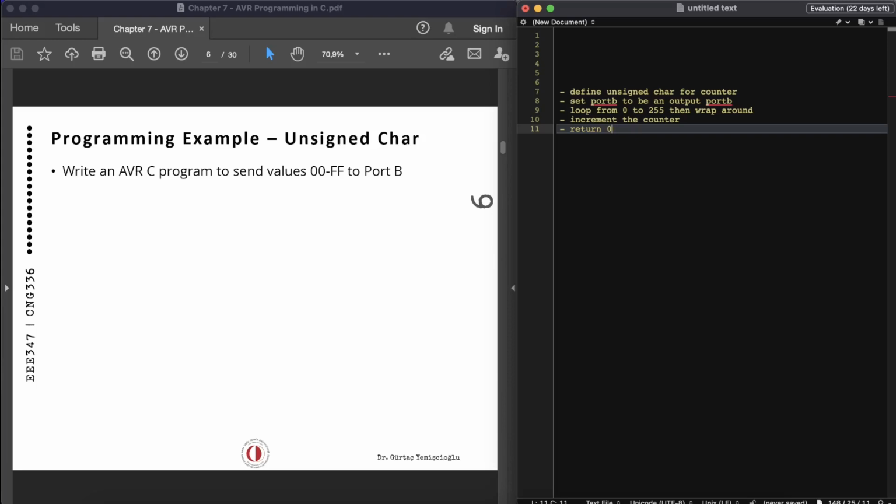Different AVR compilers might have different header files. So when we are writing these codes, we have to define the header files based on the AVR compiler. For example, if you are using the WinAVR compiler, then we have to include the avr/io.h header file. If we are using the mikroC Pro for AVR compiler, then we have to use the built_in.h header file.